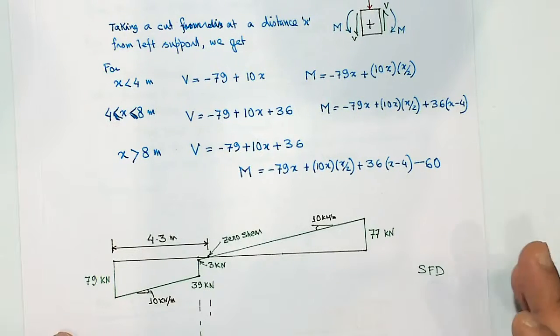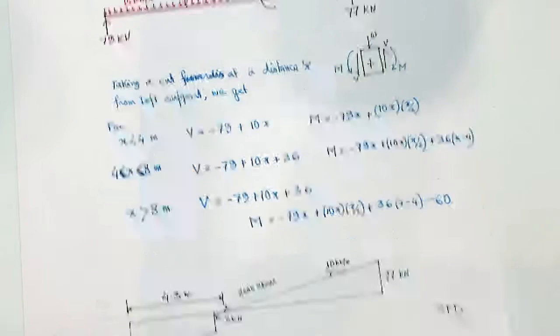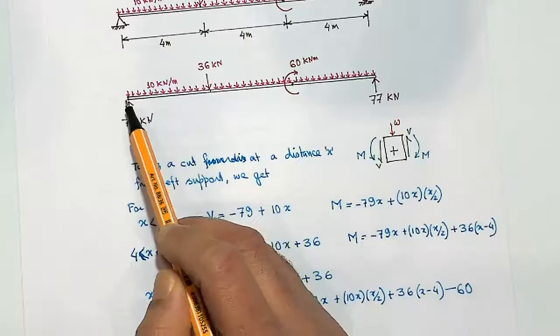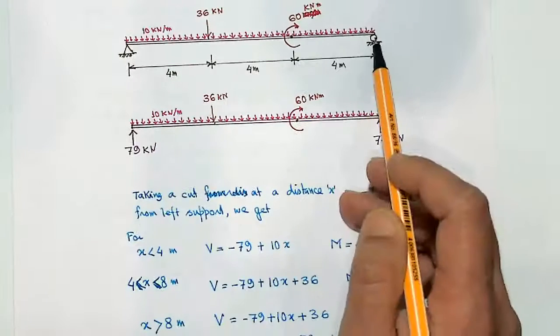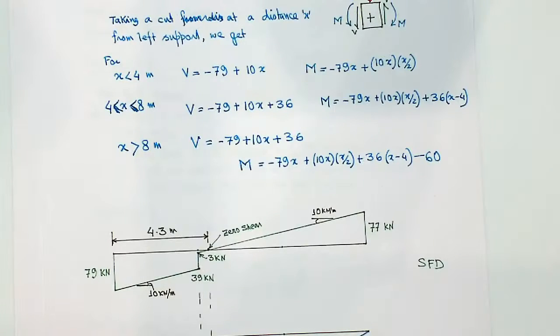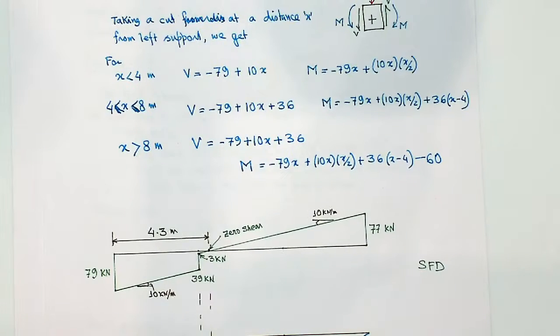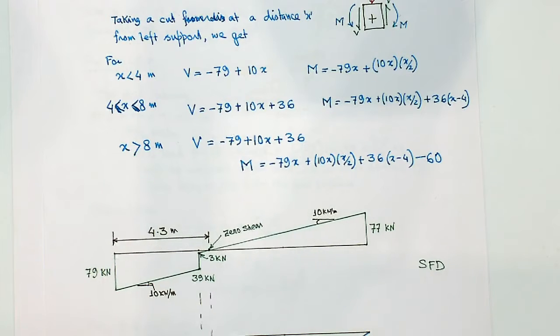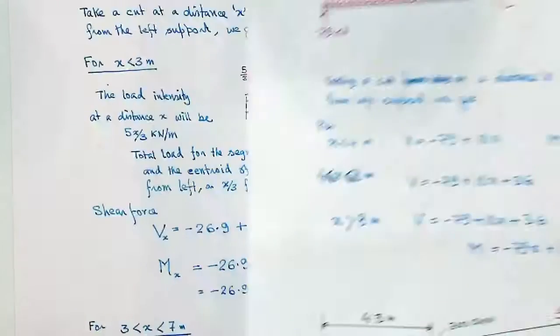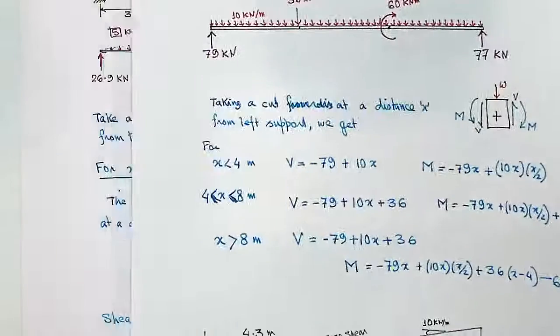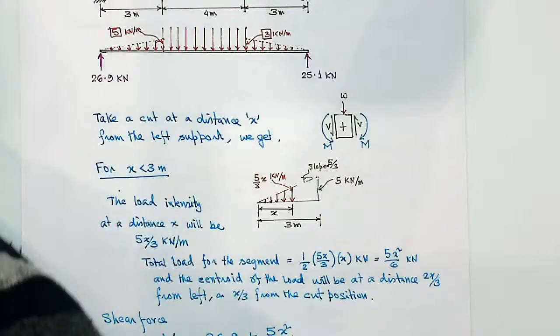it's fairly straightforward. And also another thing you should note, that whenever there is a hinge end point, bending moment is 0. So you should never put bending moment at a pinned end. And if it is a fixed end, then of course there could be bending moment. So that's problem number 2.